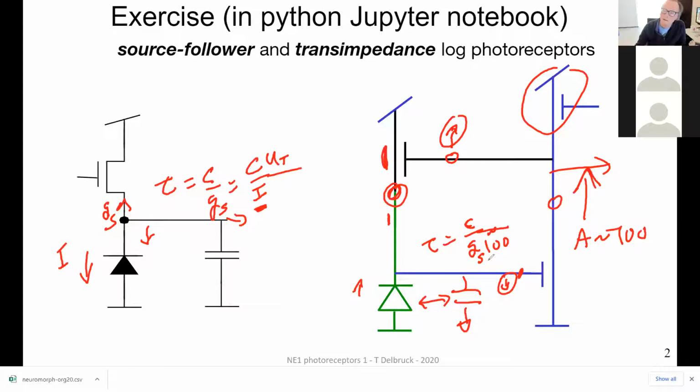So what I was asking is, is it possible to have this high gain with a single transistor arrangement that we have here? Yeah, sure. You could have this high gain. You mean with these two transistors on the right here, these blue transistors? Is it possible to get a gain of 100? Sure, it's possible. You might have to make them longer than minimum length.